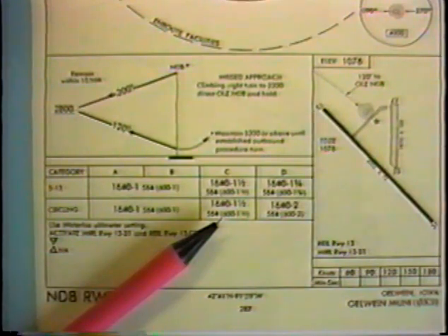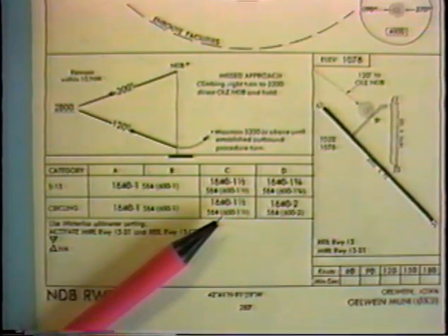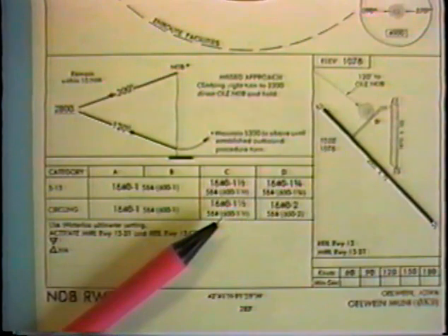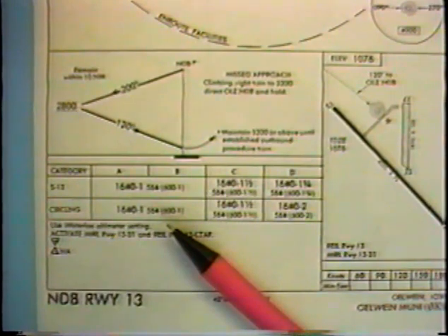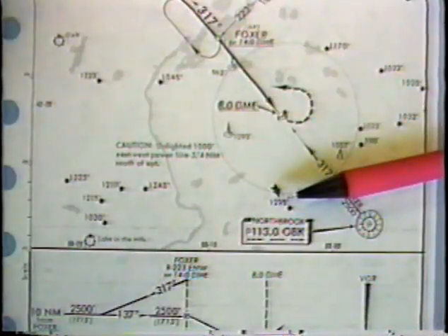The parenthetical numbers in the circle to land section are height above airport, HAA. This, plus the airport elevation, the highest point on any runway, also equals the MDA. 564 plus 1076 equals 1640. The highest obstruction on a Jeppesen plate is shown by the curving black arrow.